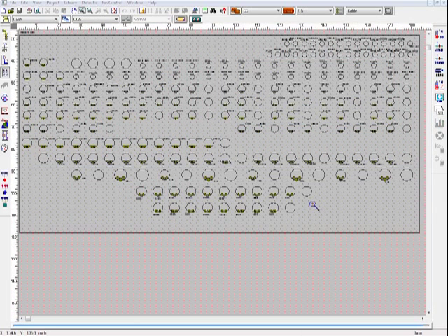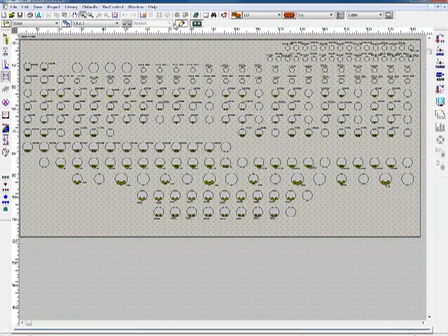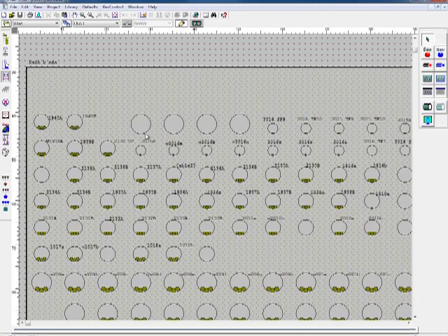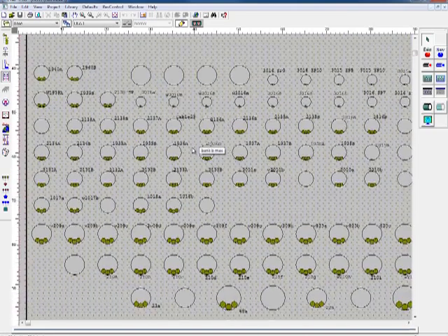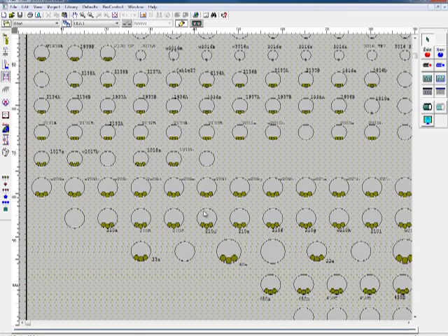As you can see in this example, we demonstrate a huge duct bank with a lot of conduits and cables, and this example is just to show you the capability of ETAP underground raceway to simulate, handle and run the calculation for a huge underground raceway system, and ETAP is capable of performing temperature analysis as well as cable current size optimizing and ampacity sizing as well.